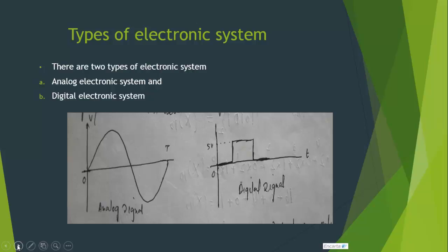Now coming to digital signals. What do you mean by a digital signal? A signal, either voltage or current, that can only have two discrete values is called a digital signal. For example, a square wave is a digital signal. It is because the signal has only two values, 0 and plus 5 volts, and no other value. These values are labeled as low and high.